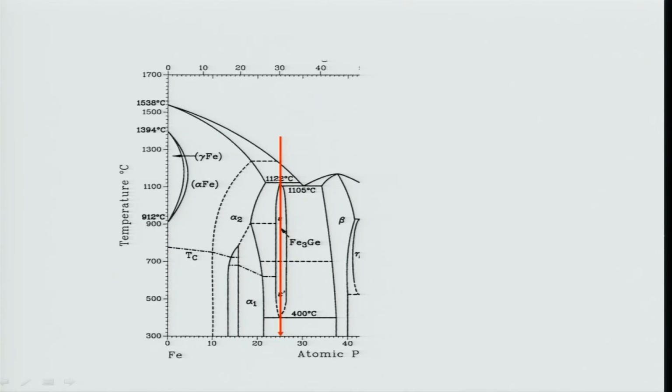But on the other hand, you have a peritectic reaction here in which alpha 2 reacts with the liquid, giving rise to epsilon. Alpha 2 has a B2 ordered structure. Basically it's a BCC crystal structure, but ordered. Epsilon has a hexagonal crystal structure with the order of DO19. And the peritectic reaction happens this way, and this peritectic reaction is followed by a eutectic reaction.